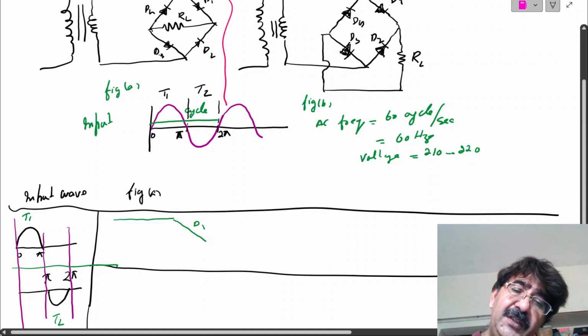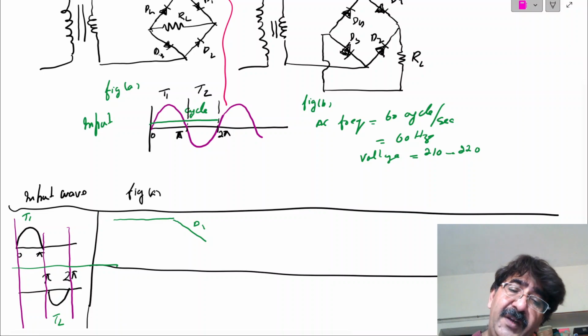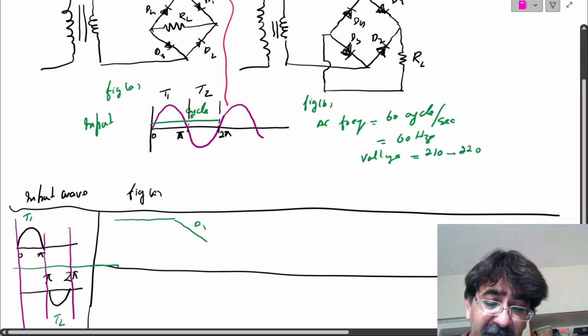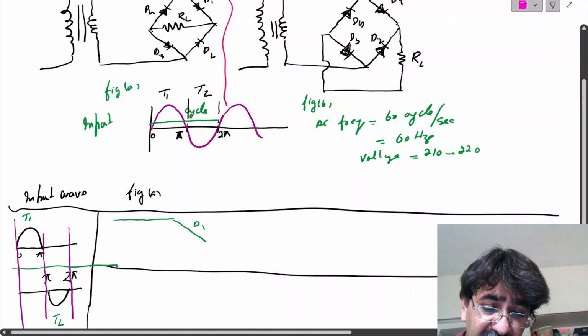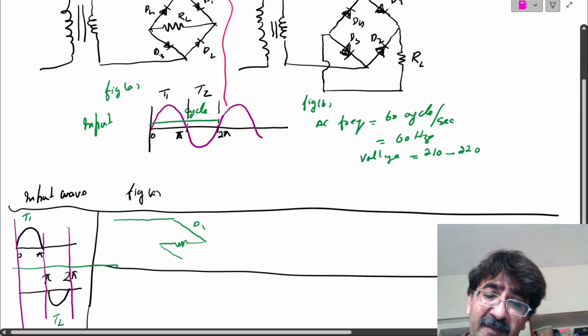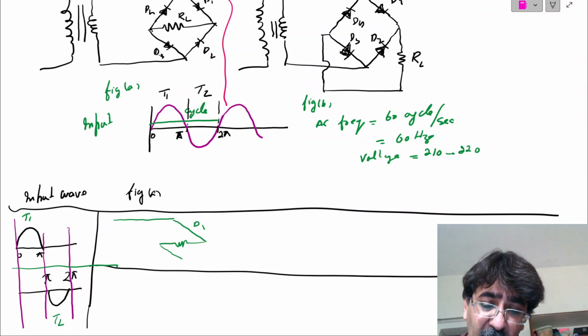But after passing through the load resistance, it will not move toward D4, because the P terminal of D4 is receiving the signal which is dropped due to the load resistance, coming from the diode and then the load resistance. So the value will be dropped. So D4 will be treated as reverse biased, but D3 will be a short circuit, forward biased, so the ripple will pass through D3, and then it goes back, so the circuit will be completed.